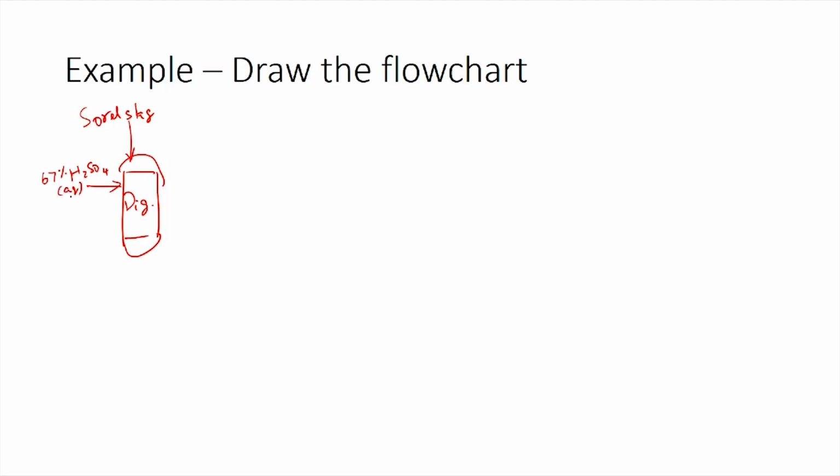And then what else do we have? We have the reactions given, and then it is also told that the theoretically required amount of sulfuric acid for sorrel slag is fed and pure oxygen is fed in the theoretical amount for all the iron in the sorrel slag. So, in addition to these two inputs, you also have another input which is the pure oxygen, fed to the digester.